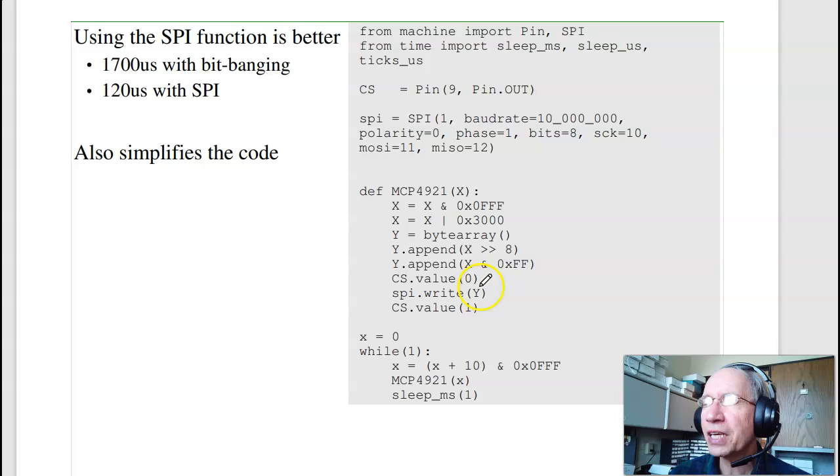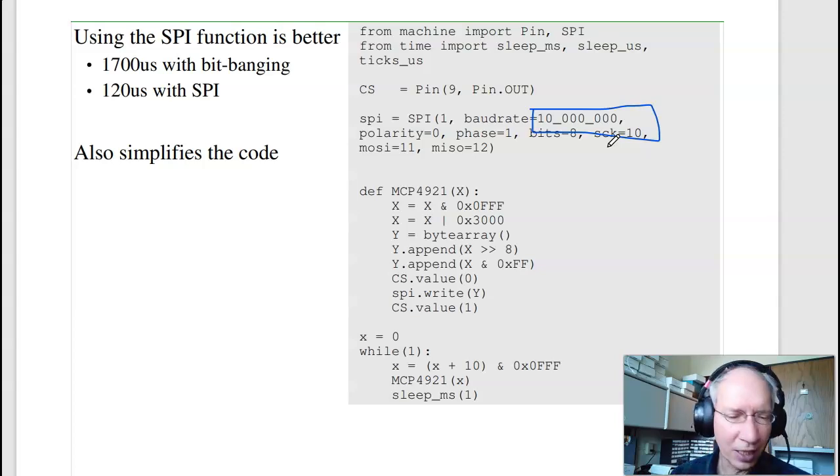And the beauty is I can do it much faster. This is sending the data at 10 megahertz. It kind of depends upon how you're setting it up. On a breadboard, you can do 10 megahertz. Occasionally on the breadboards with all my loose wires, I've got more capacitance, so I might have to drop that frequency. But on a breadboard, you can definitely do 10 to 40 megahertz.